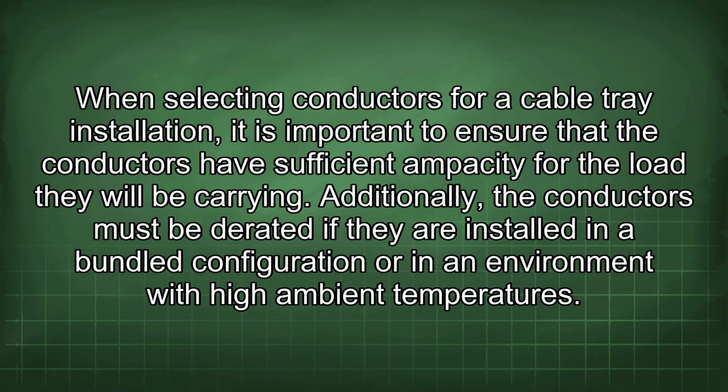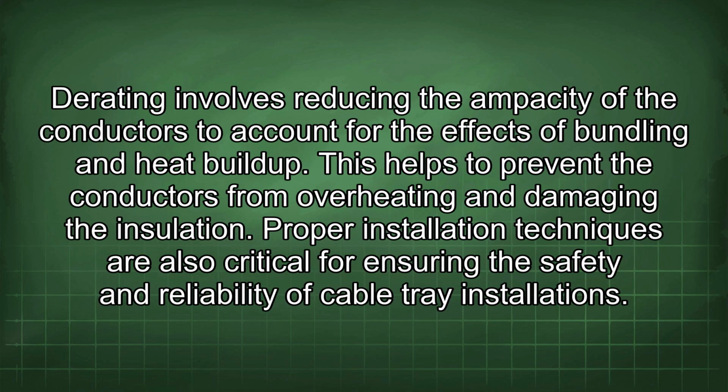Additionally, the conductors must be derated if they are installed in a bundled configuration or in an environment with high ambient temperatures. Derating involves reducing the ampacity of the conductors to account for the effects of bundling and heat buildup. This helps to prevent the conductors from overheating and damaging the insulation.